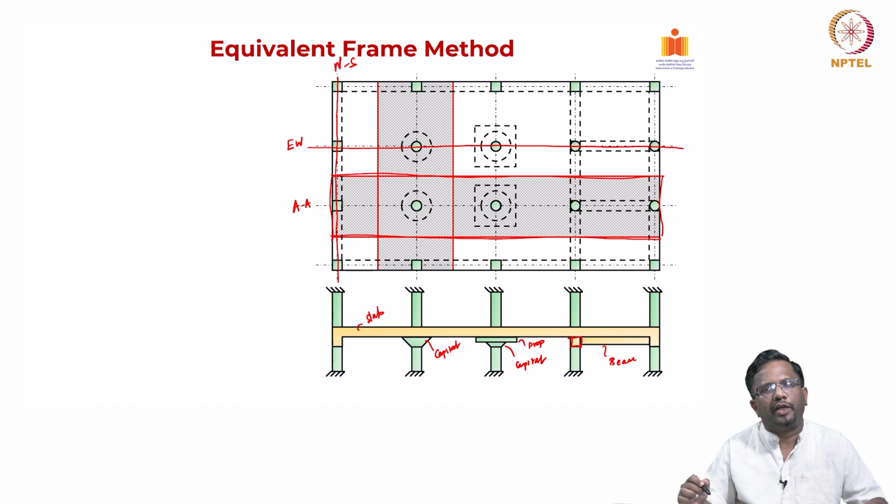And that is the reason the equivalent frame method is widely used, though nowadays design engineers use commercial software packages for doing the analysis. But it is always prudent to check the results using some simple Excel sheets that can be developed on the basis of the equivalent frame method, to verify whether your software analysis results are making sense or not. So, that is the reason for including this very important chapter, because post tensioning is very commonly used for creating slab systems, and it is highly economical as we have discussed in the previous parts. However, the analysis results have to be checked thoroughly, right.